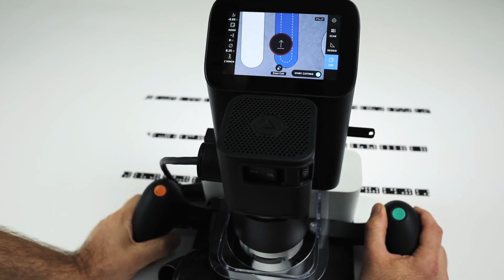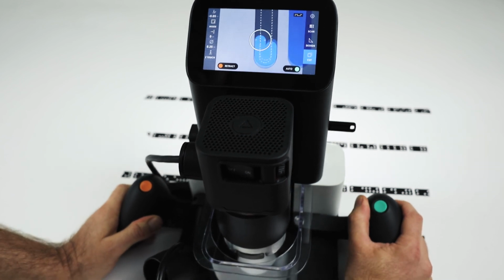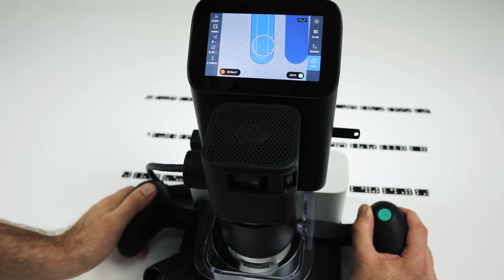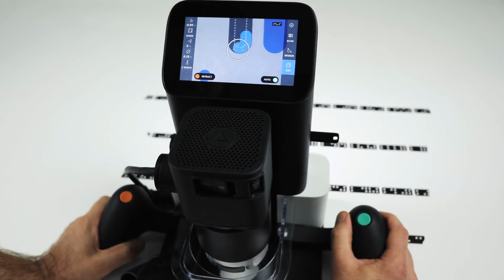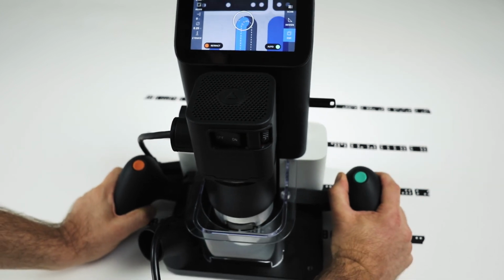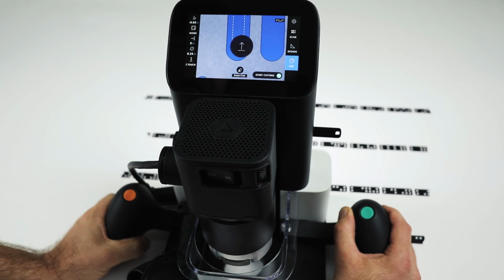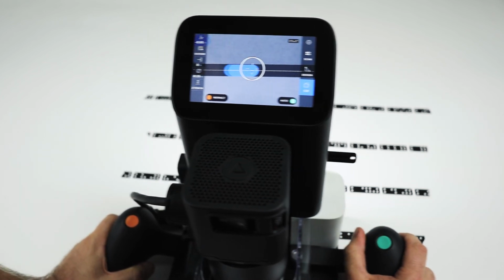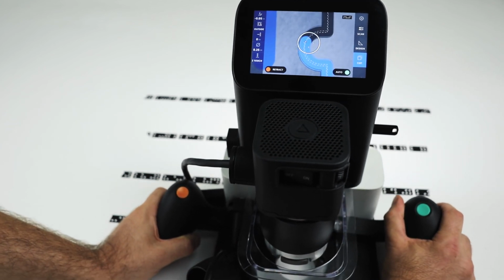Because it's 1/2 inch wide and I'm using a 1/4 inch cutter, the cut history is showing me that it can remove all that material in one pass. So we're obviously not cutting, we're hovering above the surface. My spindle's unplugged. But this is giving us a quick overview of the shapes we made and how straightforward it is to go from design to cut.